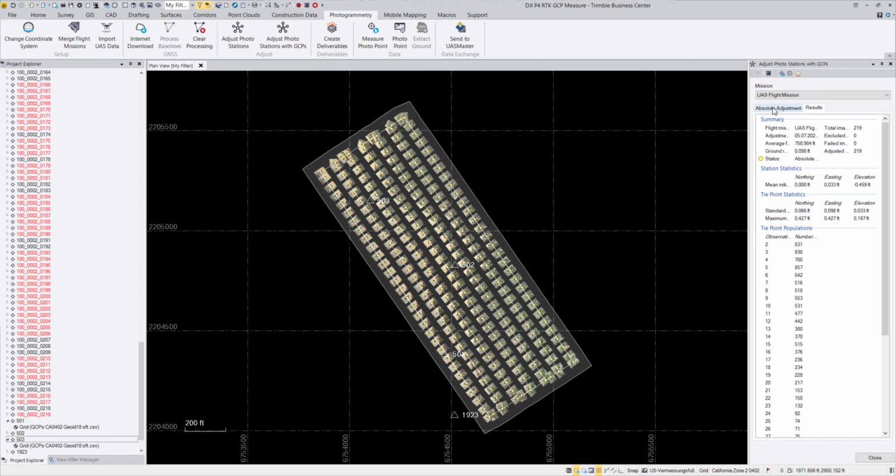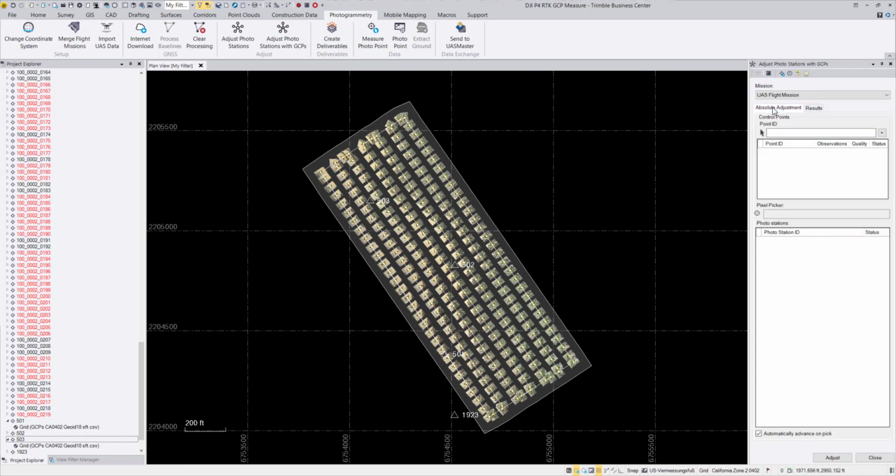And as I mentioned, we can go to the absolute adjustment part. Here I first have to click into this field, and as I mentioned, I could click in this list to fill it. Well, let's do it this way, or if we move this entry and click here, we select it from the entry. So if I say 502, or as mentioned, we can type it in, so 501, and then when you click the plus button, we will check all the predictions where this control point could be measured in.